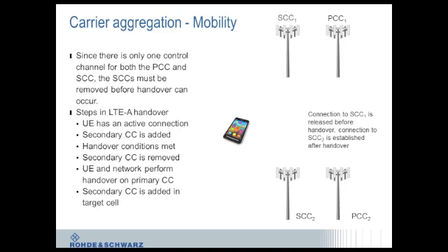The very short version of this is that in carrier aggregation, some control channels do double or triple duty. What that means is that instead of a component carrier having a full set of control channels on every component carrier, the control channels on one of the carriers, the primary component carrier, are actually used to signal information from multiple component carriers, resource allocations, etc. This has a number of benefits in terms of reducing signaling complexity, simplifying the interactions between the UEs, the network, etc.